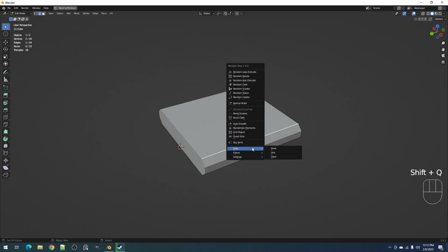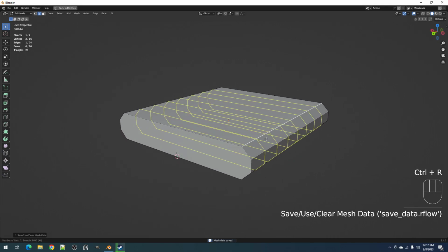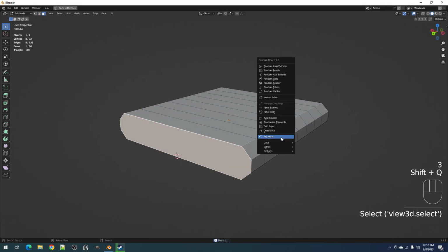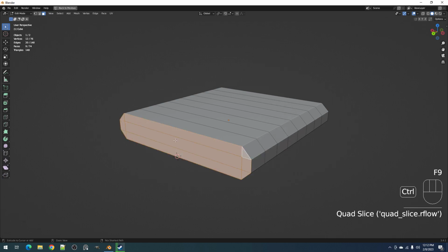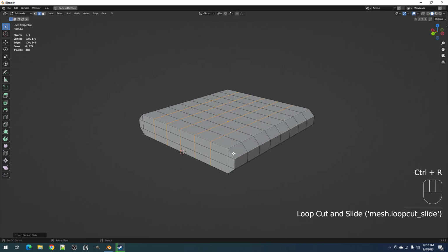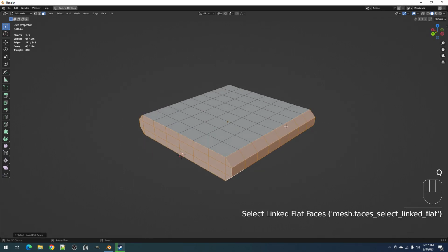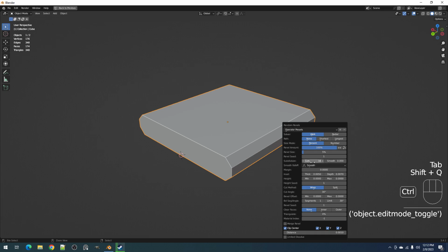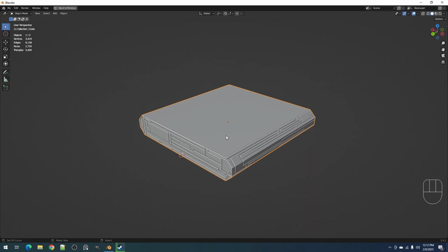There's no extraction. This is used to save the state of the mesh as it is when you use the operator. So we're going to save this state, save, and then we can change the mesh. One slice, tangent select. Then we can select the faces that we want for the randomization. Use the randomization. Whoops. Okay.